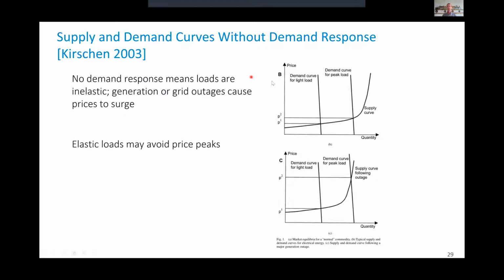Here, the motivation is essentially to reduce the reserve that is needed for coping with grid outages or generator outages. And here, this is showing the supply curve, which is very typical of what you have in existing systems where you have a large linear part. It's all globally convex, but it's linear when the production is small. And then it decreases very steeply, and there would be an asymptote here, which means there is a maximum that the system can provide here.